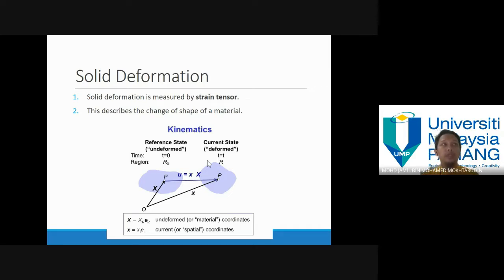So that's why your matrix sometimes becomes a 4x4 matrix, because you have x and y directions for one node and another node x and y directions as well. So you get a 4x4 matrix. And that is for 2D cases. But for 3D cases, you will have x, y, and z directions. So you will have a 6x6 matrix.